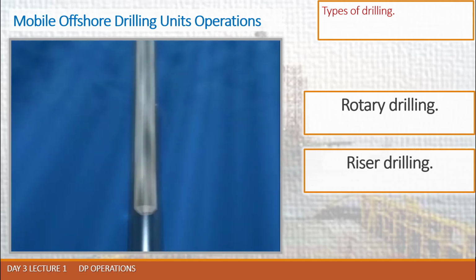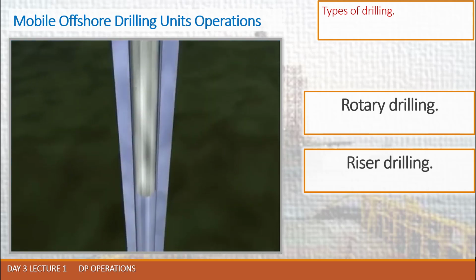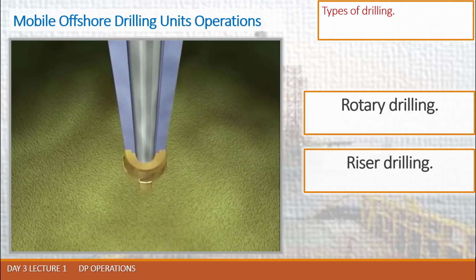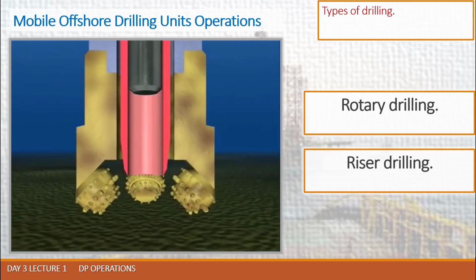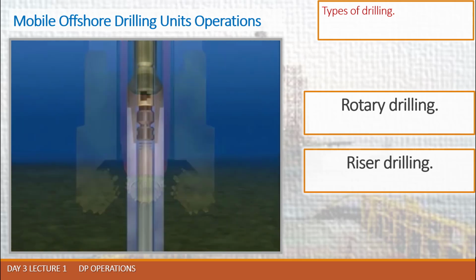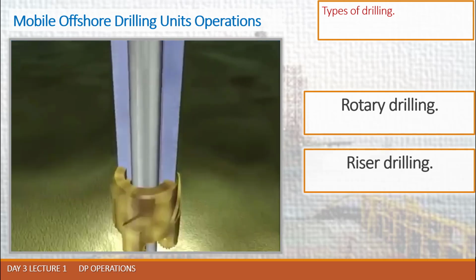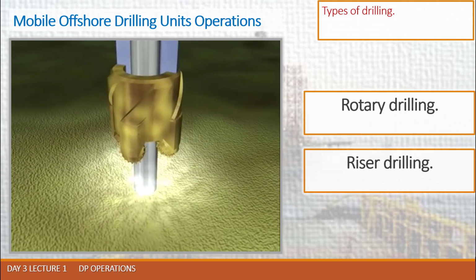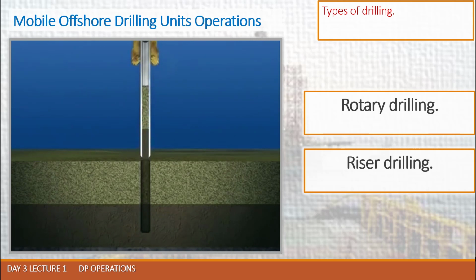Then the core barrel is run down through the drill pipe by a wire from the vessel. Once the core barrel is in place, it is ready to take a core sample. The end of the core barrel is sharpened to a knife edge so it can pierce the geological layers. Seawater is pumped into the drill pipe from the vessel to apply high pressure to the core barrel. In just 1 second, a 10-meter-long core is sampled.